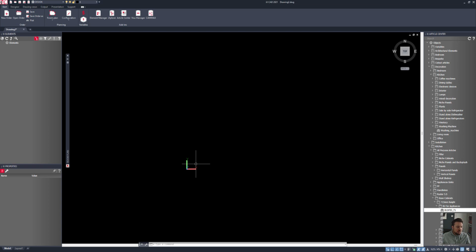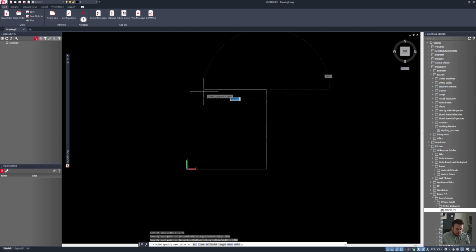So I'm going to use AutoCAD to use a polyline, so I'll start with the command PL. And then my start point will be 0, 0, 0, and then I can draw my wall. So that will be 2950. It's going to come up in this direction, 3012. It's going to come across, let's say 2656, and then down 60 millimeters, and then it comes off, and I've just got this small sort of nib